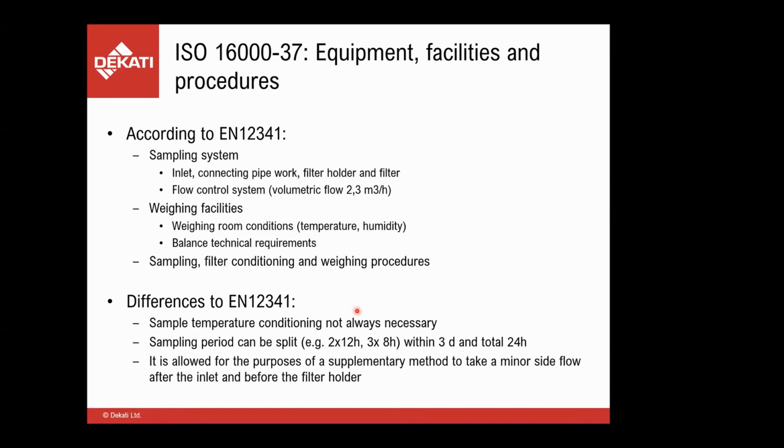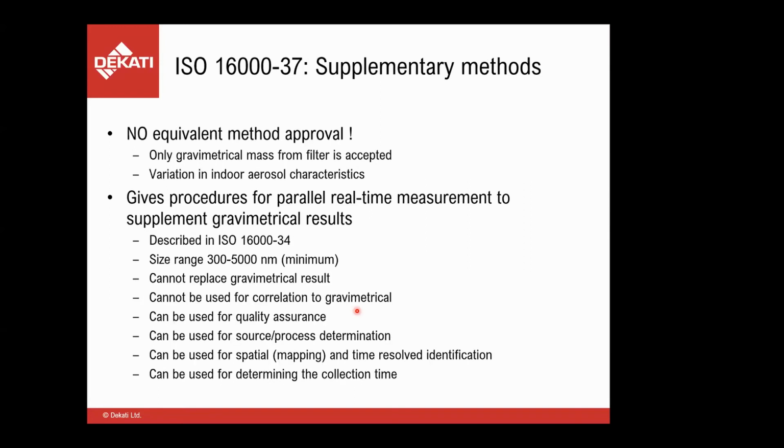And very specifically, it is allowed for the purposes of the supplementary method to take a minor side flow after the inlet and before the filter holder to do the real-time measurement. This is also not specifically banned in the EN 12341, but in this standard, it's stated that this is allowed to be done according to the ISO 16000.